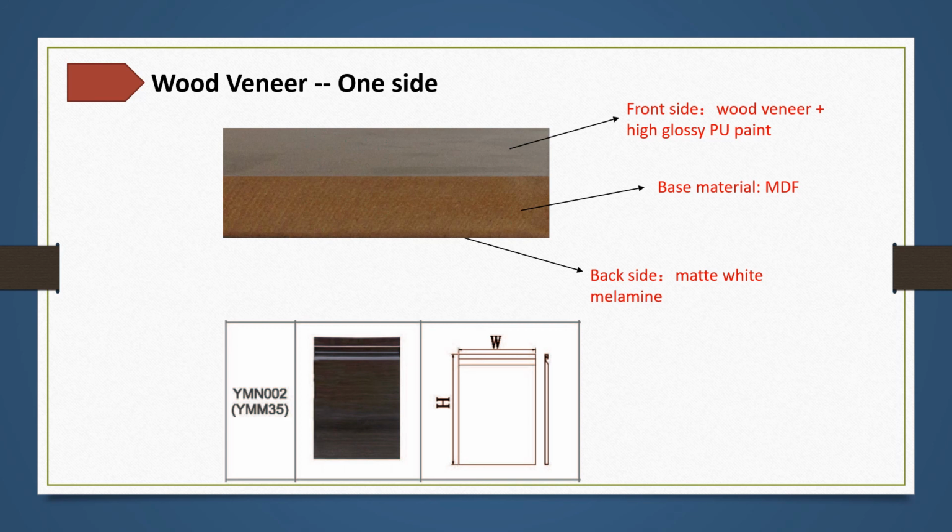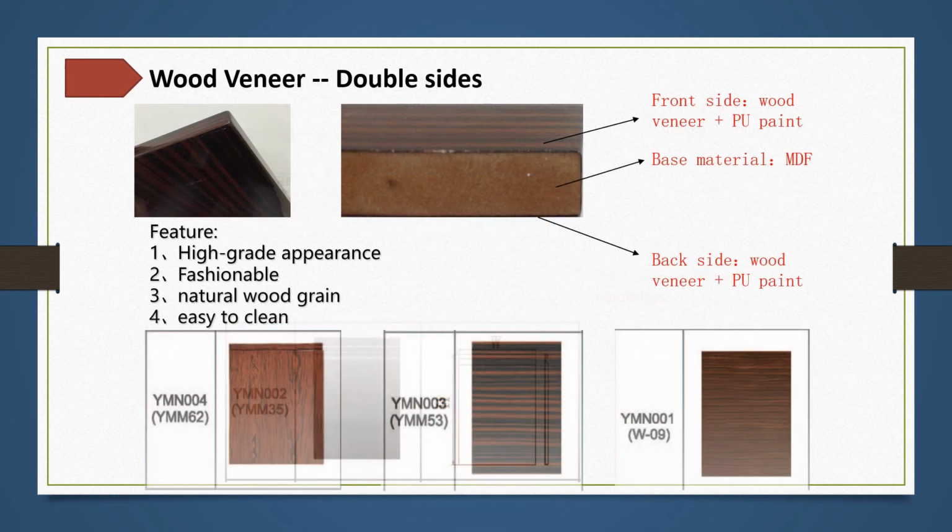But for melamine or laminate finish, we need to check and see if there are special edge bands available. For 38 thick decoration panels, it asks for 42 width edge bands. As long as you can find a 1.2 by 42 mm edge band, that means there's one available finish matched with it. For 50 thick decoration panels, the matching edge sealing size will be 1.2 by 55 mm. And here is a sheet of available decoration panel material. As time goes by, there may be new or eliminated materials, so this is only for reference.